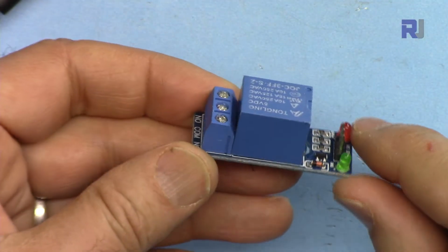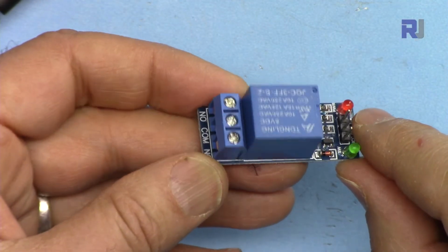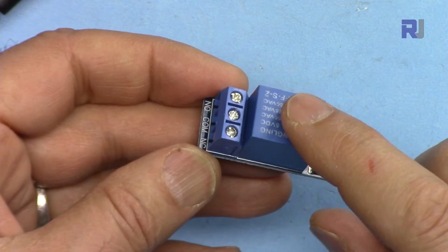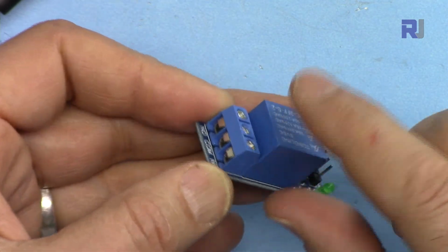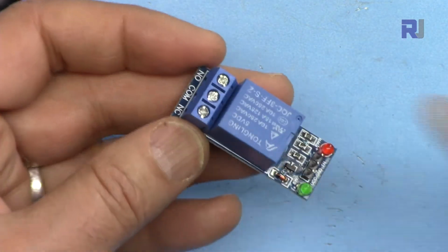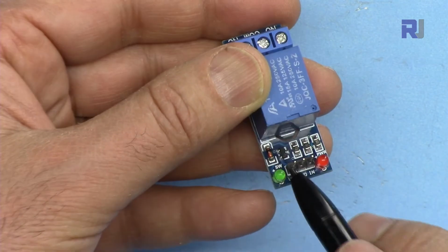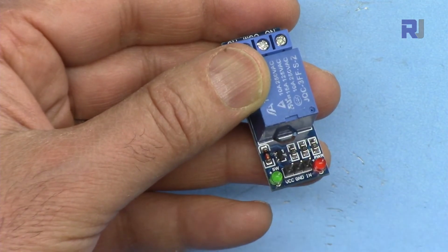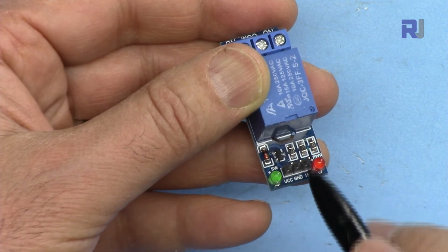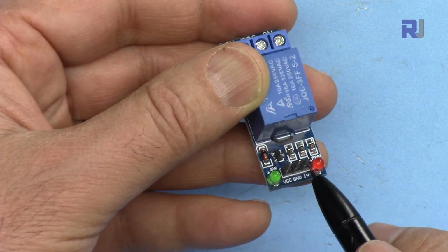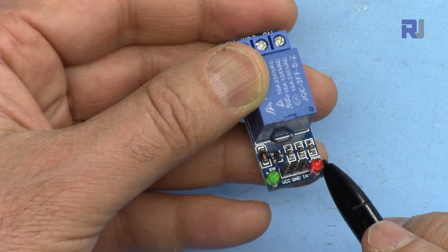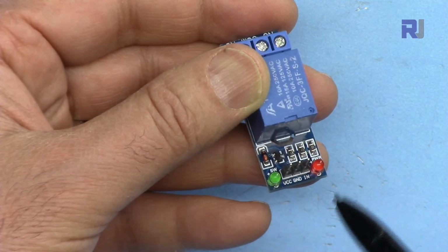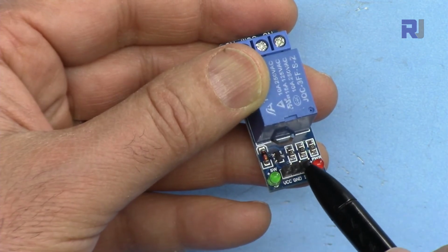Now we are using a relay to turn on and off an AC bulb or DC bulb. A relay is a module that can create a contact or turn on and off a load. It has 3 pins here. VCC will be connected to 5 volts, GND or ground will be connected to the ground of Arduino, and this will be connected to pin 2 where we send the signal. This red LED will turn on when the module has 5 volts. The green will turn on when it receives a signal.